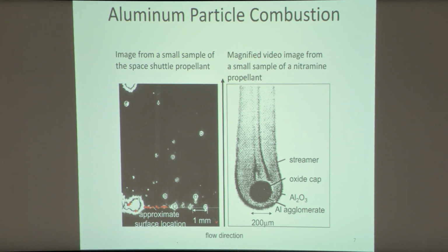And what you're seeing above it then, because of the convective gases from the binder decomposing and the AP basically having a monopropellant flame, that convective process drags the particles off the surface. And so these particles up here are burning in the gas phase above the surface. And if I were to look at this particle in natural luminosity and looking at its emission, what I would see is something like this. So this is where the agglomerate grew to about 200 micrometers in diameter.